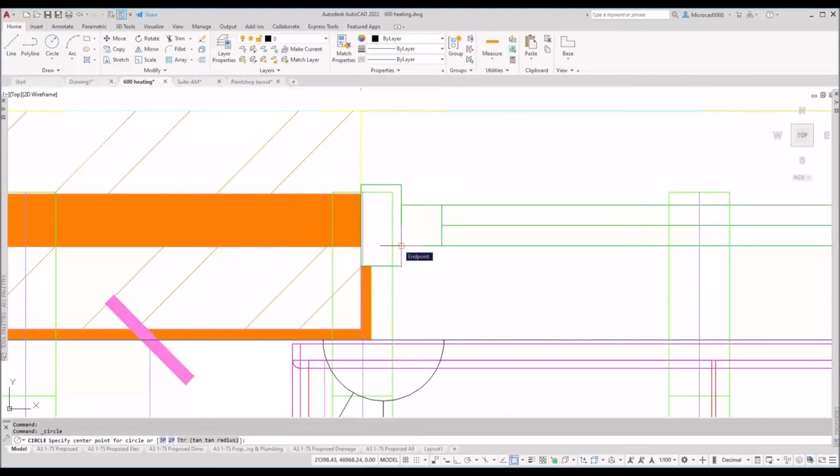Now, before I click the mouse, if I press my tab key, it jumps to the next nearest snap point. So tab, there's an intersection, tab. It's gone to the endpoint of that bottom line now, tab, a midpoint, tab. Look how it's jumping around all those different intersections, all the different snap points, as I press the tab key one by one, gradually working out away from the center where my cursor is. So I'm pressing the tab key and click with the mouse, and it's got a different point altogether, jumping around to the one you want.